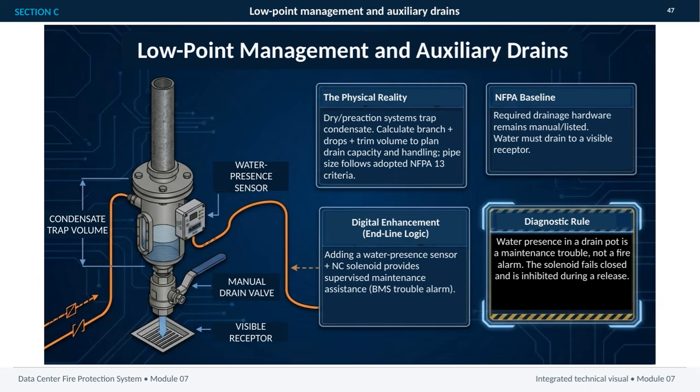The key diagnostic distinction is water presence is a maintenance trouble, not a fire alarm. The solenoid fails closed, and it is inhibited during a release, so the enhancement supports monitoring without interfering with system operation during an actual event.